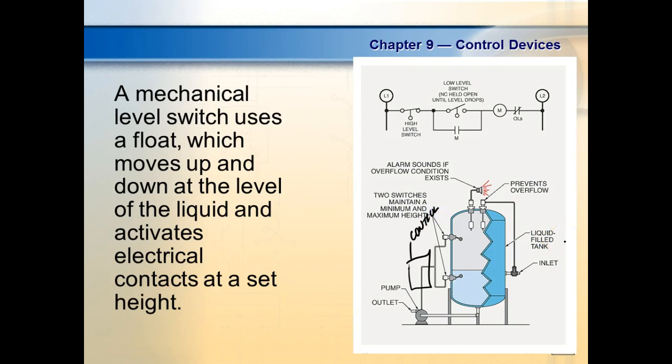So what would happen is, if the level is below this one, the pump should come on. This is not going to do anything, right? Understand? And it's going to fill up until it does what? It reaches that one. And then it's going to sit there, right? How long? Until the pump drains it out. And when it drops down to here, it should do what? Start again. So there's going to have to be some logic to that.